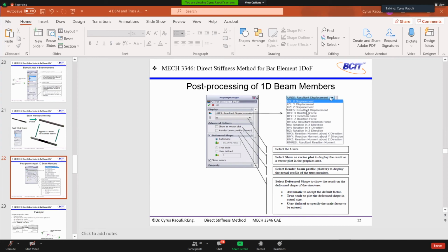And we had one example, 4-1, chapter 4, example 1, where you had two fixtures at both ends, and you had one equation, sigma Fx equals 0, and two unknowns. And you can use the direct stiffness method to solve the problem. Same thing happens here. SolidWorks is going to solve and give you the reaction forces.